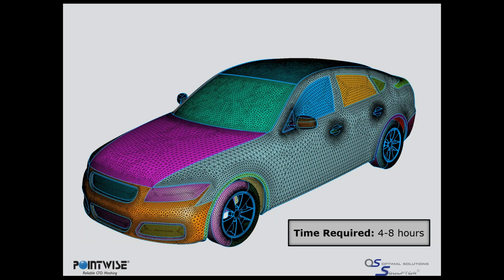Okay. So the time required for this, if you look at this surface mesh, it's a little bit different. It's a little coarser than the one that we created in the video, but same concepts. The time required to clean this up, to mesh it, then create the volume mesh, conservatively is about 4 to 8 hours, depending on how much experience you have with the tool. Okay. So if you think about it, if we're going to be running an optimization and we're going to be creating hundreds, if not thousands of designs based off of this model, that is a very small price to pay for creating a very high quality mesh from the beginning.